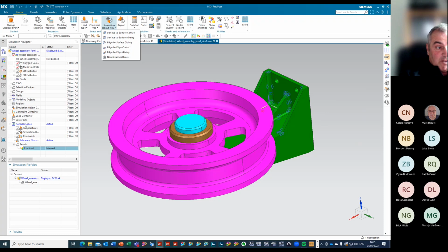If I change it to something else, then I might see a different list of capabilities. You only see the icons that are related to the solver that you're doing. Notice here I can't apply forces, etc., like we could previously, because 103 doesn't allow us to do that. These are the only boundary conditions we could apply from a loading perspective.